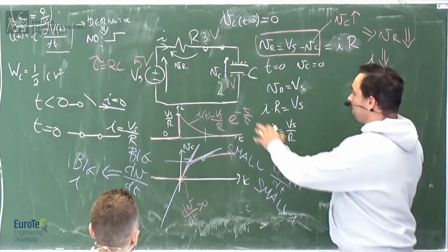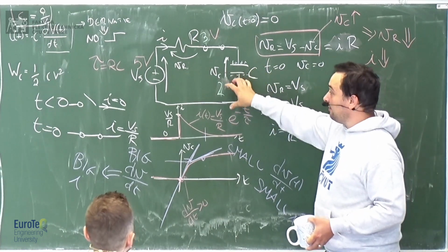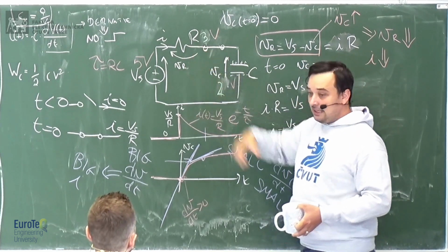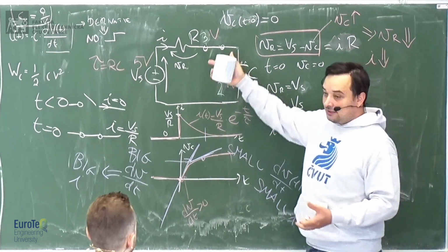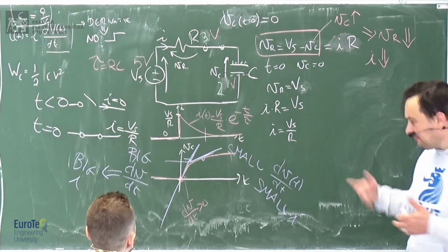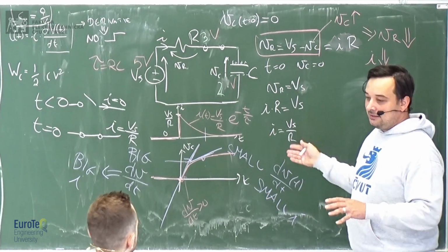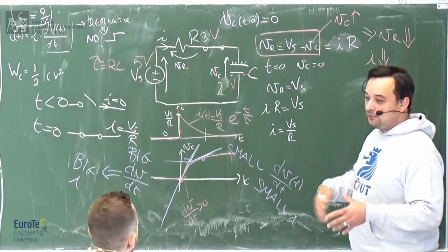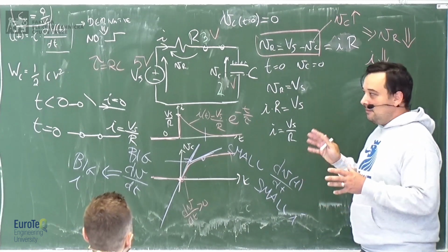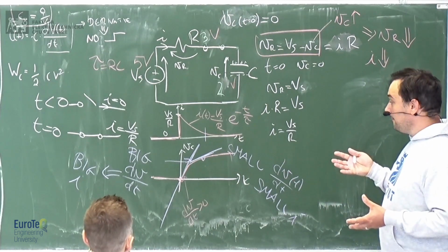What happens? You give some current, you know that the current charges up the capacitor, therefore this capacitor eats up voltage available for the resistance, so the current will drop. Yes, it's a first order differential equation. If you have a second reactive component, like LC, you really need to go into the mathematics to see when it oscillates and when not. It's not so intuitive anymore. But at least for the first order transient, you can see physically what happens.